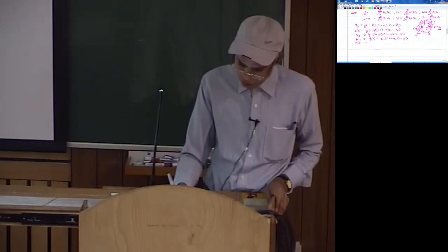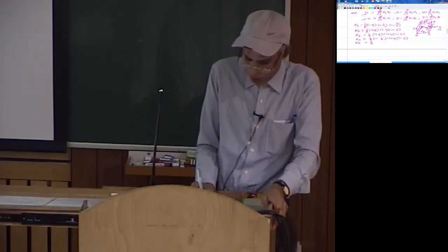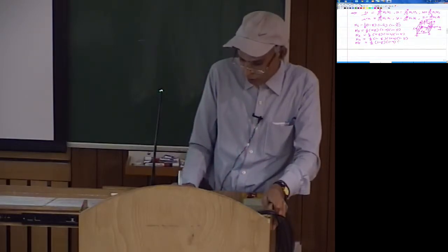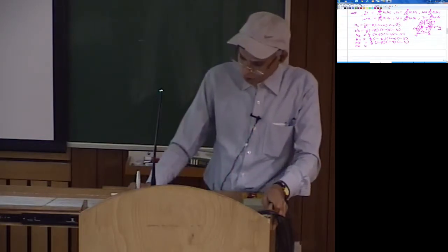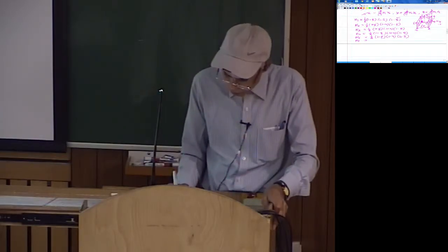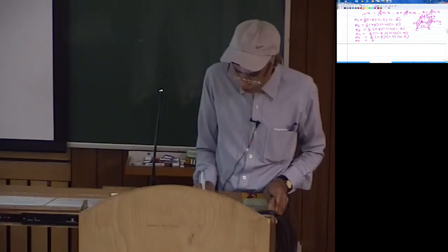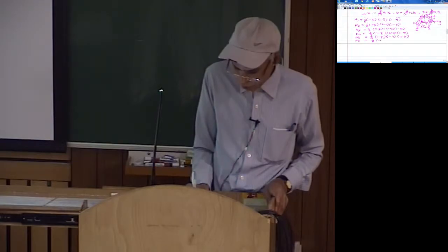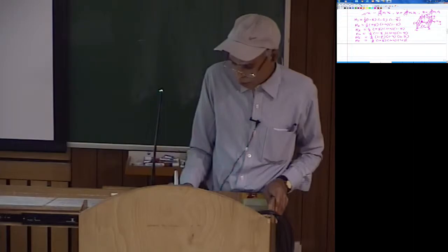So in the shape function of N1, if you replace zeta by minus zeta, you get actually the shape function. So 1 by 8, 1 minus xi, 1 minus eta, 1 minus zeta. So similarly N6, this is going to be plus. So N6 is then going to be, now the sign of xi would change, so this would become 1 plus xi, 1 minus eta and 1 plus zeta.